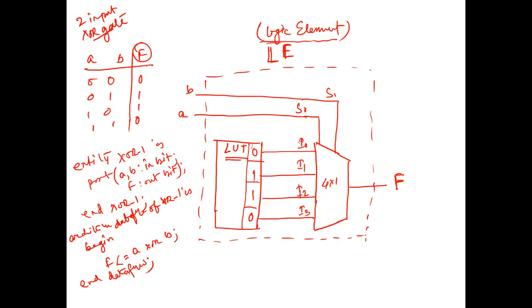So what we do in the case of the FPGA: we create a project, then under the project we create a module. Then we write this program, and after that we synthesize whatever we wrote in the module, and then we download it into the FPGA.